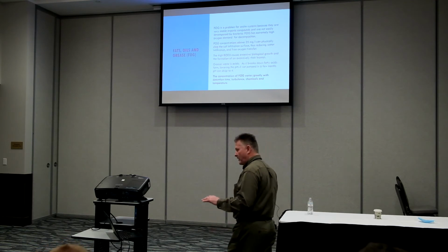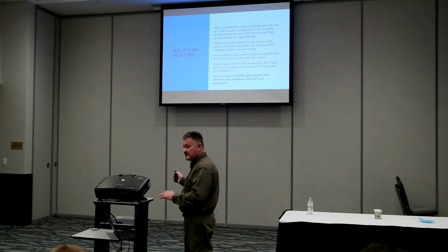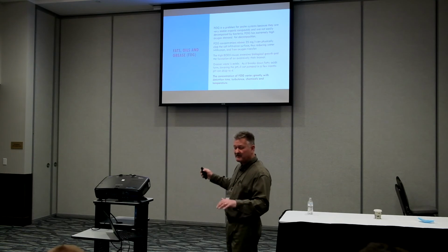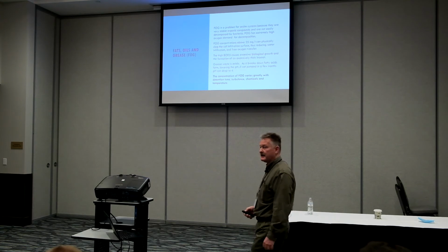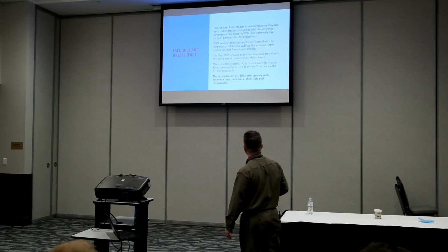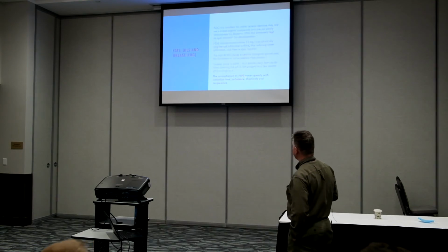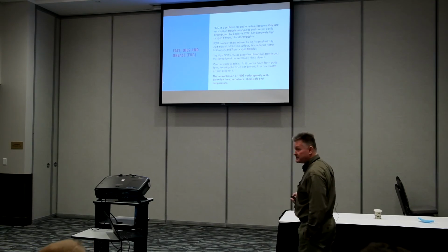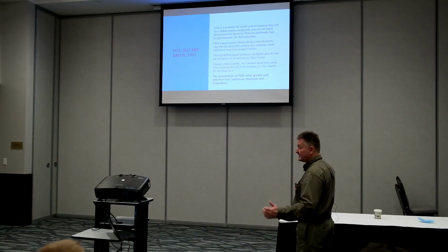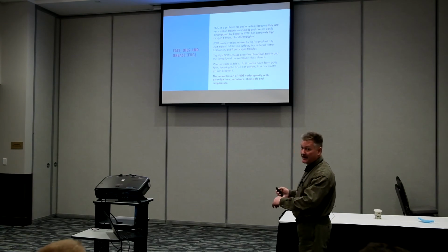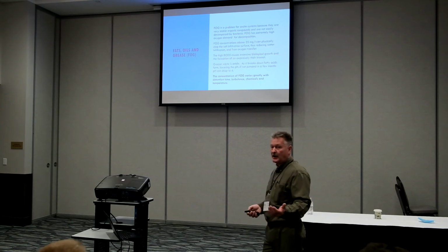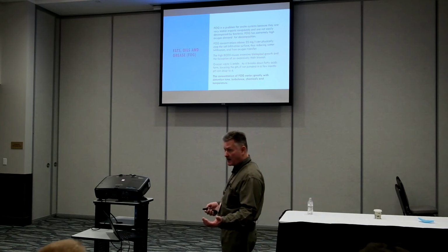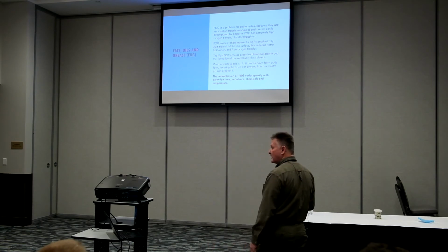In fact, some people are evaluating, instead of asking when do we pump that septic tank, do we base it on pH versus sludge judging it and measuring the physical separation in there. Fat, oil, and grease concentrations vary greatly with the detention time and turbulence in that tank, so we have to make sure we have large enough tanks, and we have to watch how that input is coming into the tank to reduce turbulence. Low temperature chemical dishwashers are going to discharge fat, oil, and grease.